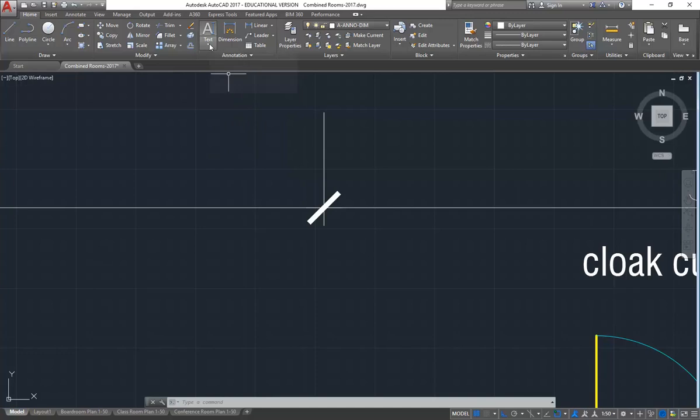And then I'll, again, draw single line text. Enter twice, and now type C. And again, it seems strange, but enter twice to finish, because enter the first time just moves down to the next line. Single line text does that. So enter again finishes it.